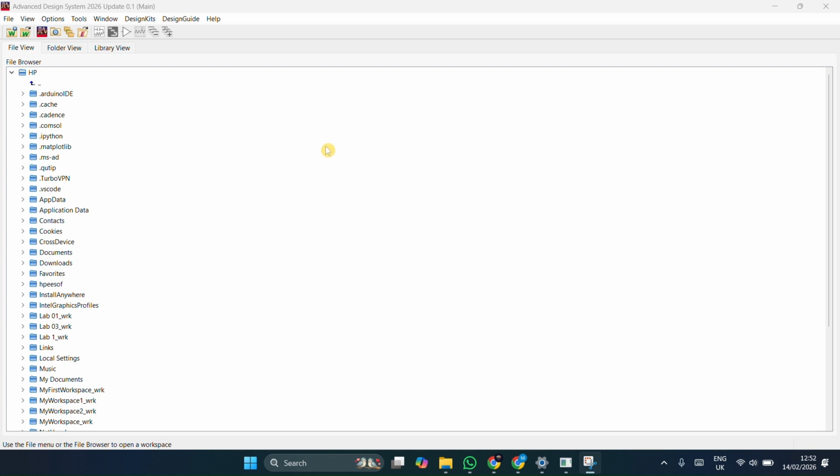In today's tutorial, we are going to design and simulate a microstrip transmission line using ADS software. We will use Linecalc to find our physical dimensions for a 2.4 GHz design and then verify everything with an EM simulation. So let's jump in.